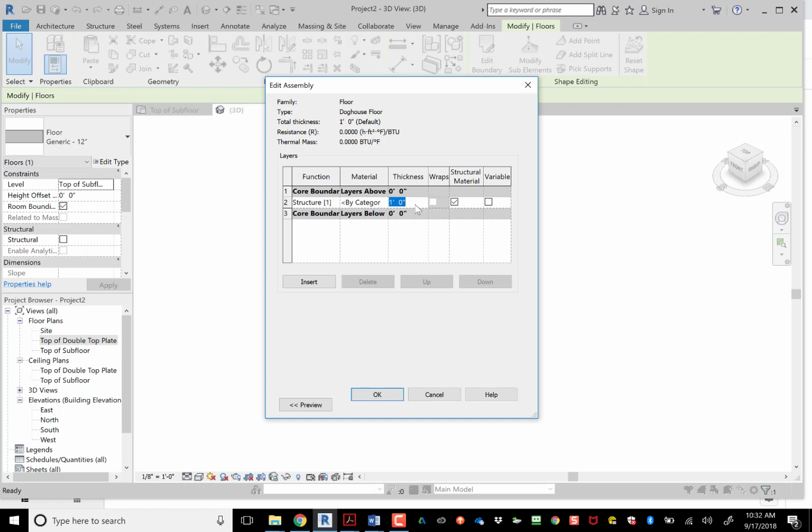I think if I remember correctly, we used 2x6s. Again, you can check the textbooks to see if your span will work with 2x6 or if it will work with 2x4. But I'm just gonna say it's gonna work with 2x6s. What did you guys just learn? 2x6 is actually, what is it? 1.5 by 5.5, good. So I'm gonna set that at 5.5 inches.